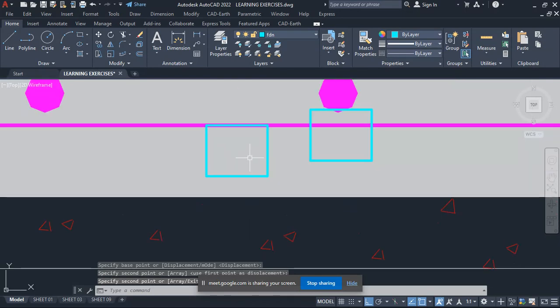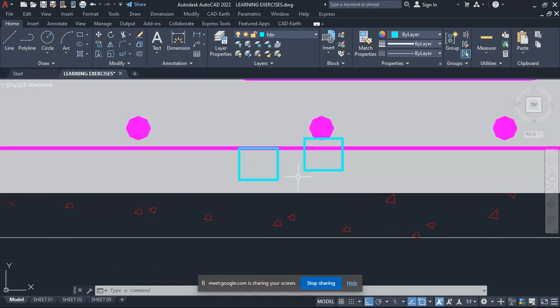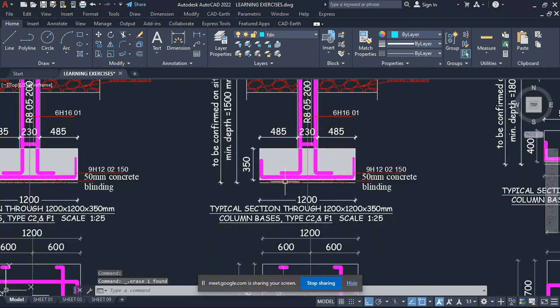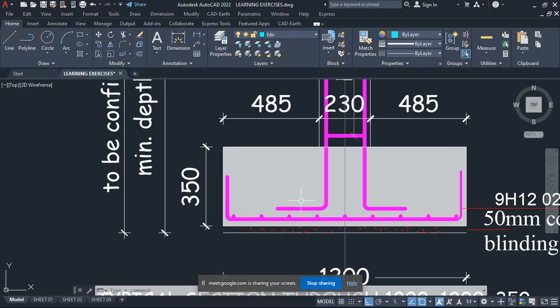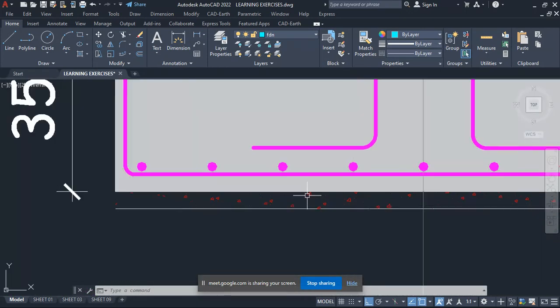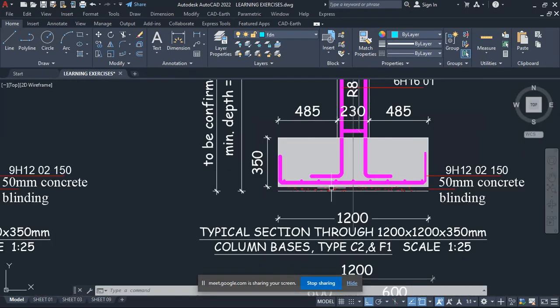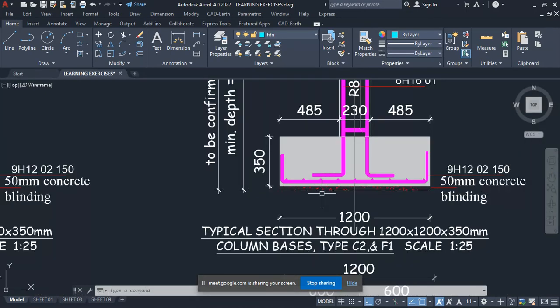Now this spacer is very important because the lesser space you have, the more the environment will get in touch with this bar, and you know what happens to iron when it gets water. It is rusting. So some structures are just sitting, we don't know what is happening. Anything can happen, in the case of a catastrophe, because surely you can't get a 5-story structure seated in a swamp and give it a cover of 1 inch and expect it to last 200 years. Surely it is practically impossible.